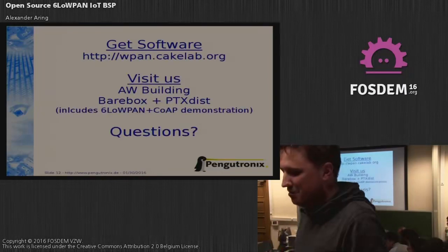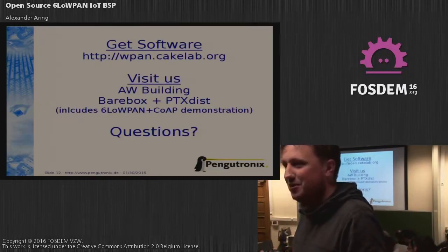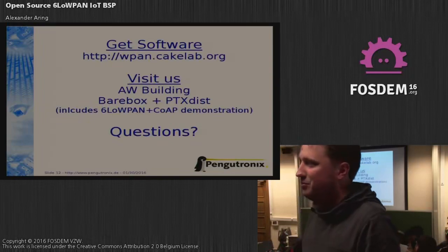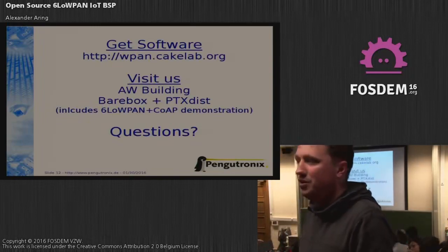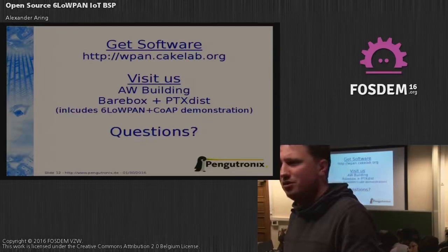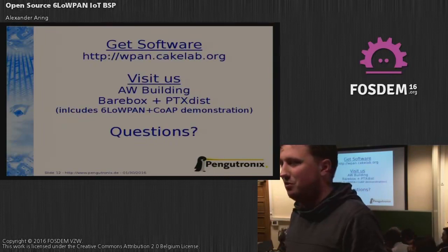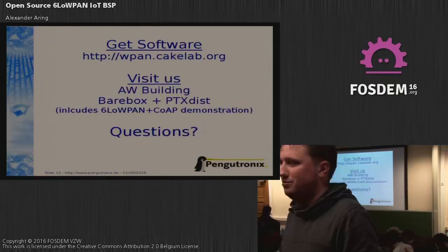I think what you're searching for is the RPL implementation. And by mesh network, you mean mesh-under routing? At the lowest level possible, like RF. The typical problem is to get information from the RF part to the upper level, like received signal range.